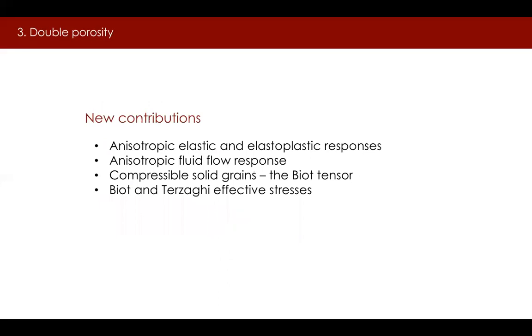New contributions of this presentation include a mechanistic framework for incorporating anisotropy in the elastic and elastoplastic responses, anisotropy in the fluid flow response, the introduction of a Biot tensor for the case where the compressibility of the solid grains is comparable to the compressibility of the solid skeleton, and a distinction between the Biot and Terzaghi effective stresses in the elastoplastic range.